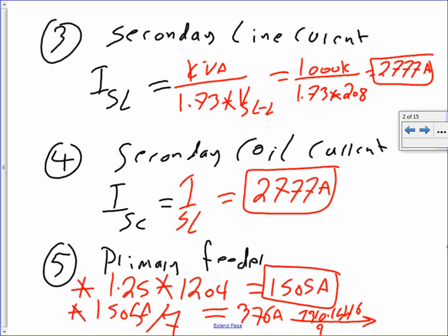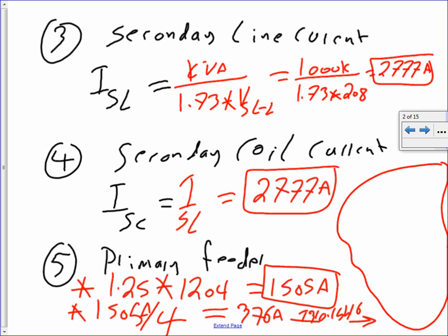Take this one, guys, to table 310.15(B)(16) on the 75-degree column. And here's what you're going to get when you go there. It's the 75-degree column, we don't use 90. This is 4 runs, guys, my apologies. My 4 looks like 7s here. That's why I can't read my handwriting. So this is a 4, so that makes a lot of sense.